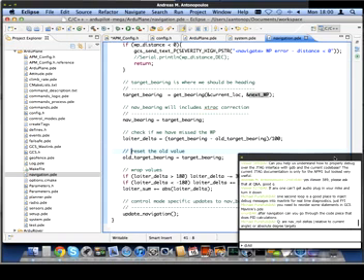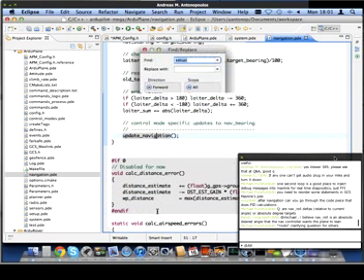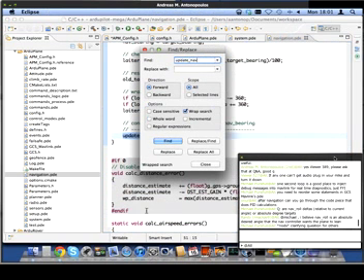There's a few little bits regarding loiter. You can see, for example, loiter delta. In the current code, it's no longer as critical as it used to be. It's trying to check whether we have gone right around a waypoint and missed it completely. We've got some new code that went in a couple of weeks ago that is based on crossing a finish line, crossing a plane that is perpendicular to the path between the previous and next waypoint. And in fact, this loiter delta is no longer critical. It's still in there, but it's very unlikely to be triggered in any normal sort of flight conditions.